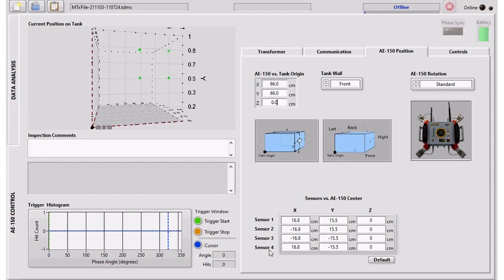This section here is if you are working with a small transformer that has a lot of mechanical obstacles around it, and the sensors must be detached. It could be an option. So you will use the accessories holder to hold the sensors separately on their own.